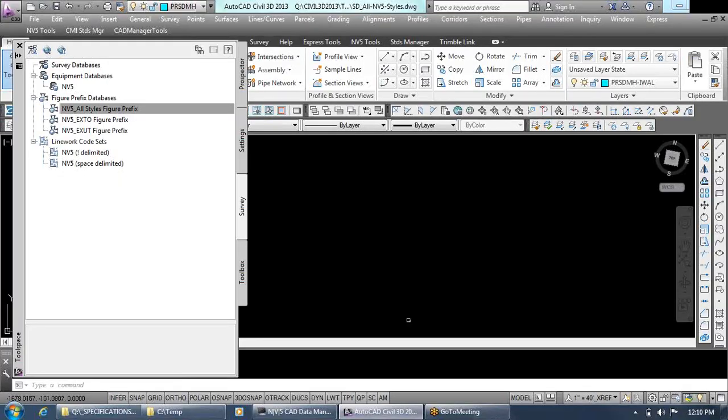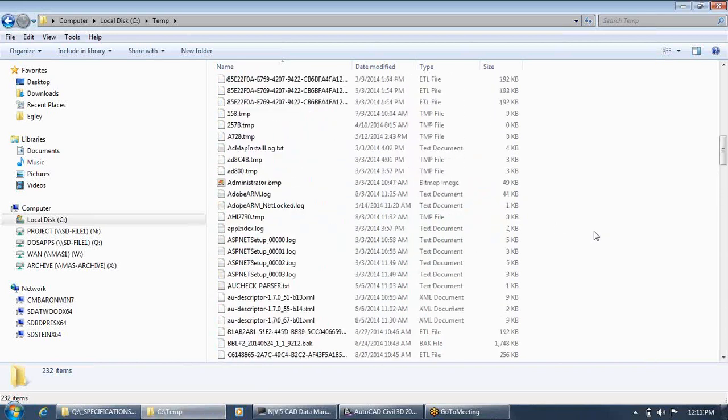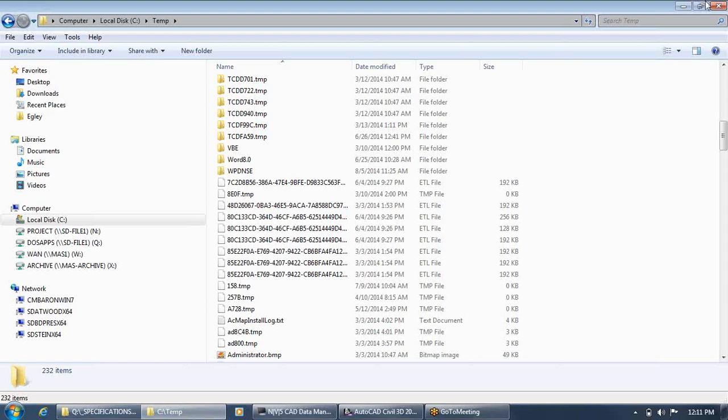Anytime you open up a file in AutoCAD, it's writing about 12 different files to that folder. Over time, that folder can become inundated with a lot of items. Just the way this computer system works, it's very helpful to clean out the temp file folder once in a while. Nothing here is really needed. You can delete it all without any consequence.